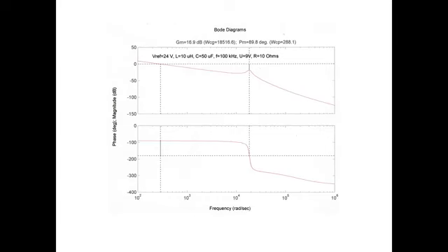So this would tell you at 10 ohms, which is the most lightly damped point in that, this says we have a gain margin of 17 dB and a phase margin of almost 90 degrees. So any control guy will tell you that's a super stable system. You're not going to be unstable. No worries. And they're right. The output's not going to blow up. Whether it's acceptable or not is another question. Okay, and that's what you got to think about.